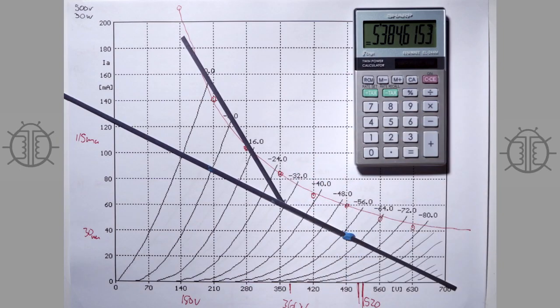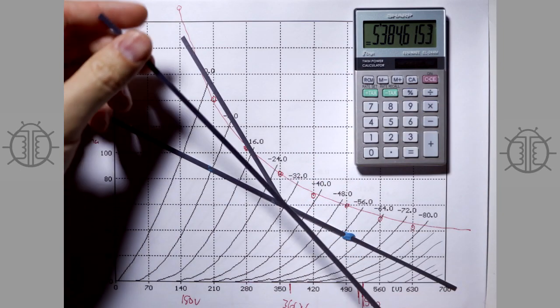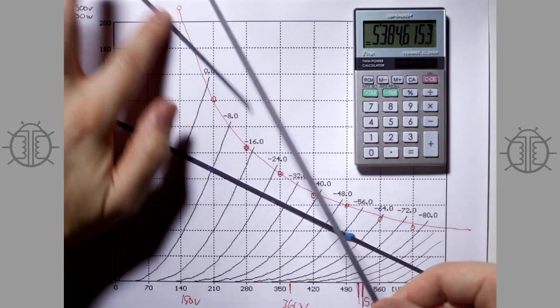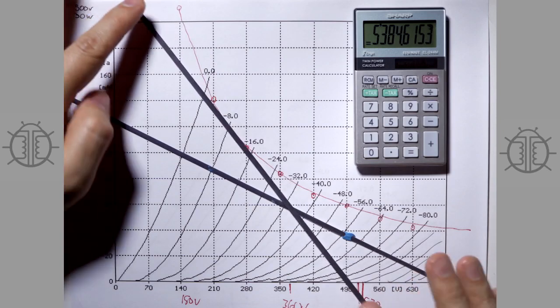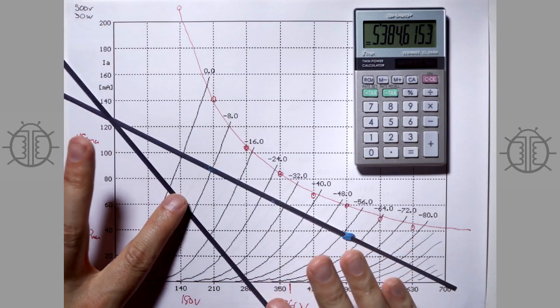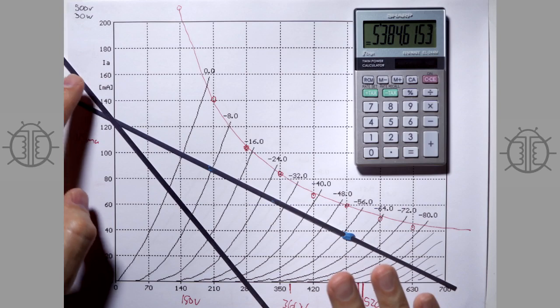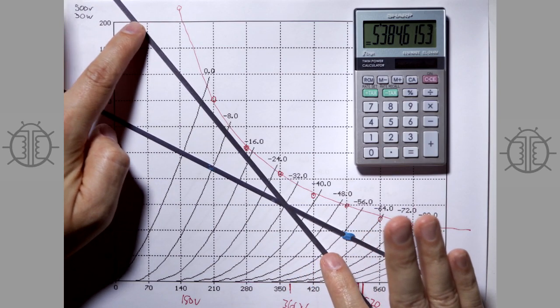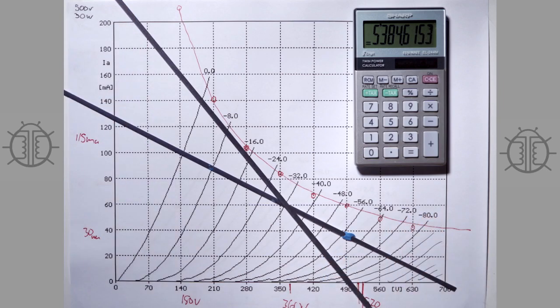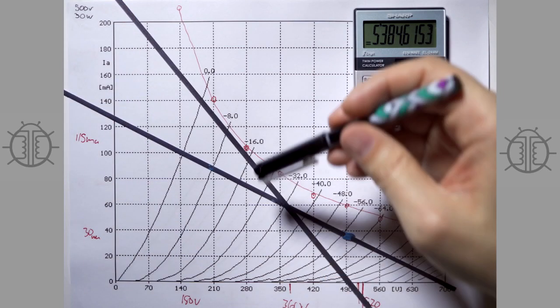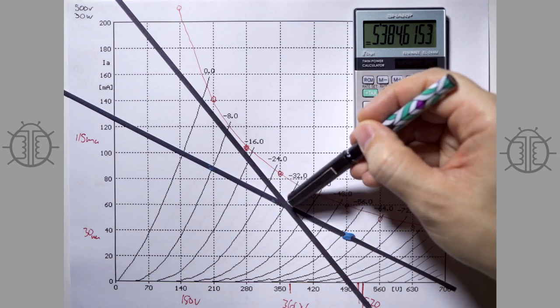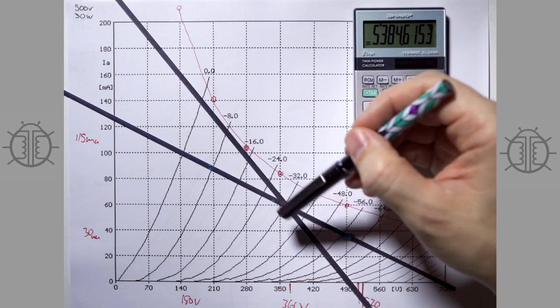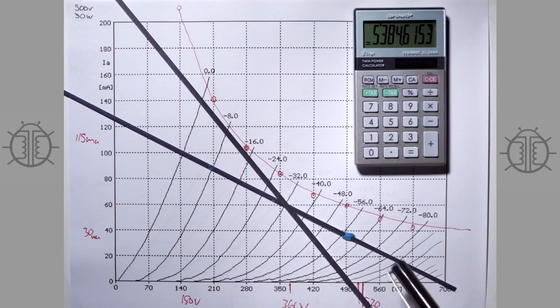And you could actually chart that out. You could take your longer load line and bring it down here and find your 2.5K, your exact slope, and then just move it up to the point at which it's going to transition from Class A to Class B. Now, in reality, this is more of a curve and not so much of an immediate transition, because you can see that the tube doesn't cut off immediately.